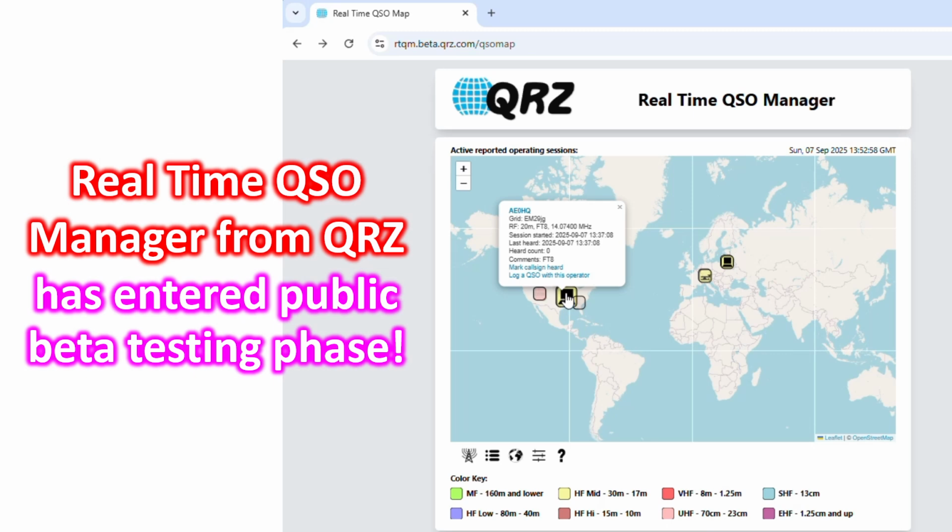This is a digital mode. You can see 20 meter FT8, standard FT8 frequency here. And the grid and call sign are given there. These are faded spots. You can see compared to this one, this is very bright. That means the spot has been over there for quite some time, and as time passes, this becomes faded. This is also digital because you have the symbol of the computer. This is CW. You can see the Morse key.